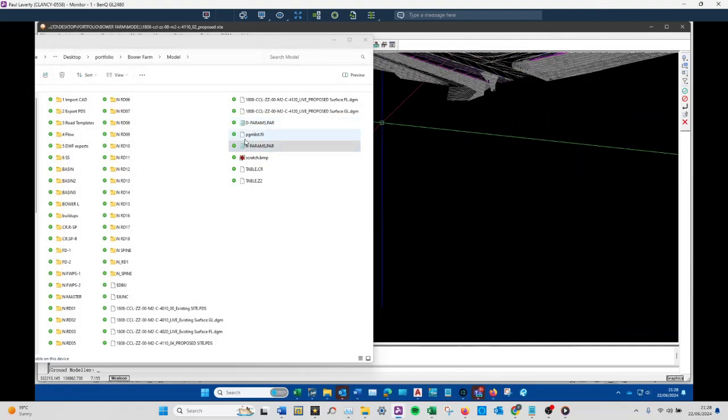And in all honesty, when you have your PDS project file folder template, those will already be in there, and you can tweak these. I'll get more into that when we go into the various different modules. But if you tweak them in that, because maybe you want the minimum distance between manholes to be lesser because you want to have nodes between points on a drainage system, by changing that in your template folder and you bring it into this, it's already sorted out, and again, you don't have to touch it.